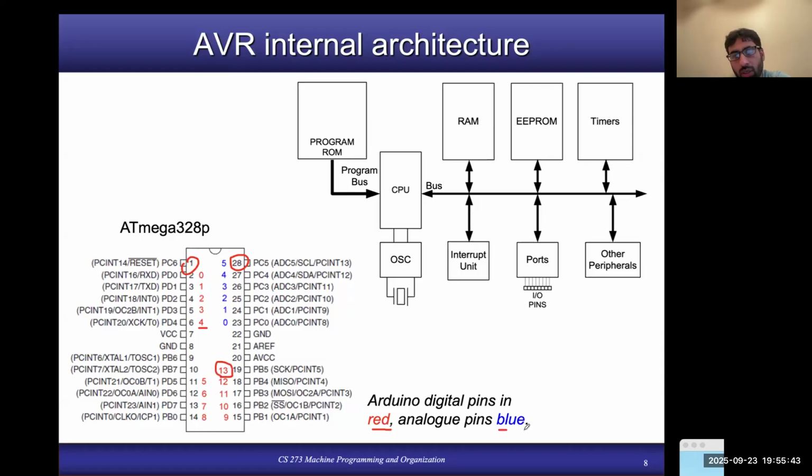And the blue numbered pins on the Arduino are analog pins. They are for reading values, for example, if in a project you want to read values from sensors. Those values are analog values, not in digital form. So if we want to do that, we will interface our sensors with one of these inputs, 0 to 5.